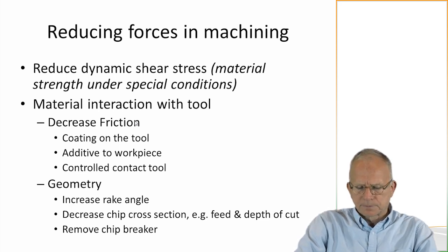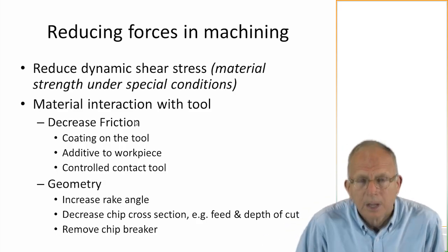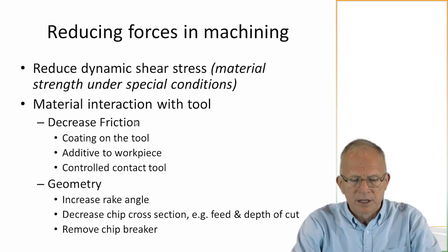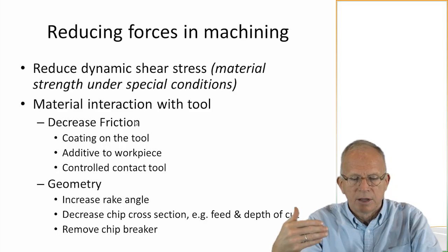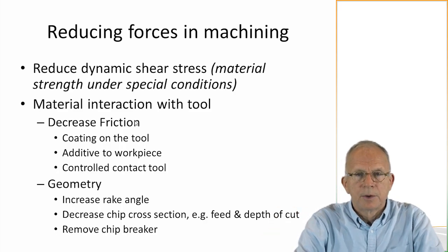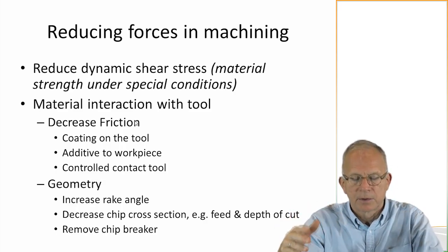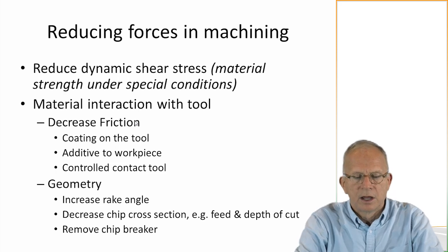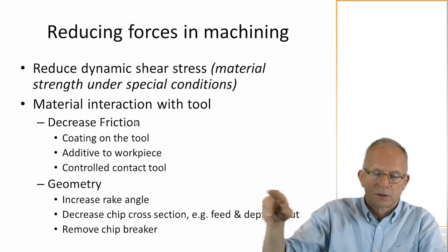Now, one of the interesting things to note about chatter too is that there are stability lobes. And so the tendency, if you're machining and you run into chatter, is to back off on the feed or on the speed. But if you're setting up for a large production run, you're going to slow things up that way. And so you can increase the speed or increase sometimes the tool overhang and get away from a chatter regime that way because it goes in distinct lobes.